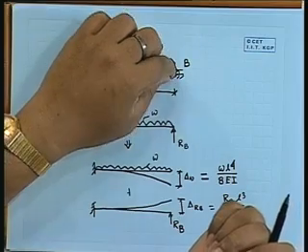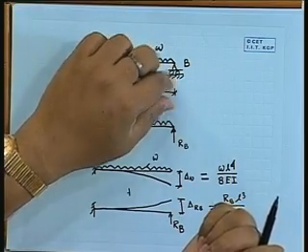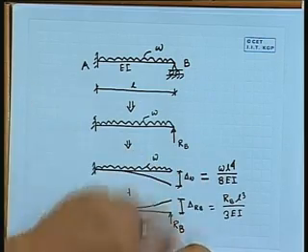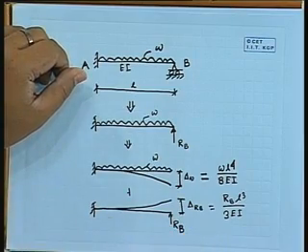So in that manner, this is not necessarily the only place where we can remove and put the load. There might be some other possibility, so the same problem can be solved in a different manner. But in all the cases, our extra unknown degree of indeterminacy is 1. So we are writing only one equation, we are trying to match one deflection, and from there we are getting the result.